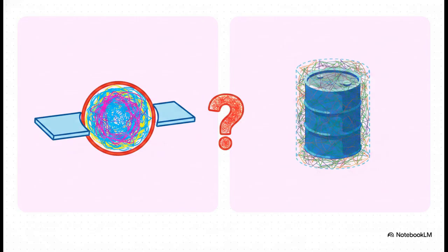Now, a super common mistake we see is people confusing circularity with cylindricity. Look, circularity is strictly a 2D tolerance evaluating individual cross-sections. You basically slice the part conceptually and just look at that one specific slice. Cylindricity, on the other hand, is a 3D tolerance. It measures straightness and roundness along the entire length of the part, all at the same time.